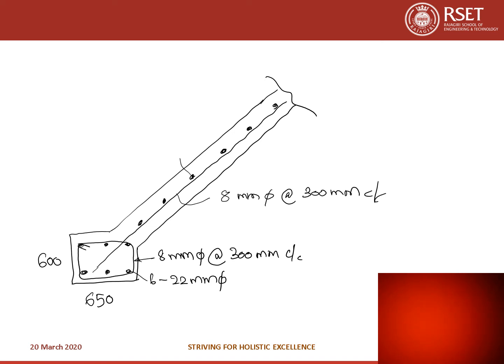This reinforcement will be in the meridional direction, and this will be in the latitude direction, 8 mm diameter at 300 mm center to center.